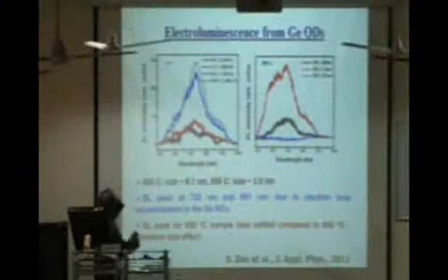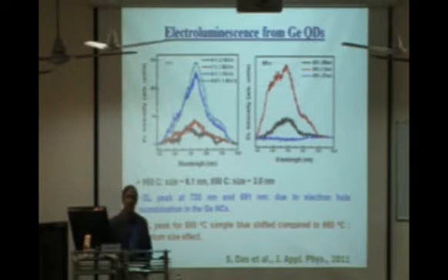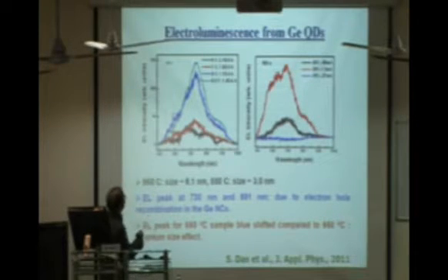Of course, we get a very nice emission, as you see in these two different samples I am showing. This is a better sample. Typically you start getting the emission at around 6 volt. As you start increasing the bias voltage, the emission intensity, or electroluminescence intensity, goes up. So here you don't have to excite the quantum dot with a laser. This is an electrically operable device.